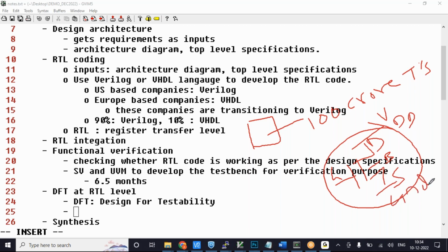For example, assume due to something, this also got connected to VDD. It was supposed to connect to something else. What happened? Because we are manufacturing at a very small level. What is the level we are manufacturing at? Nanometer level. What can happen? A metal got deposited here, some metal got spilled over. It's metal deposition, right? That's how a chip is made. These two got shorted. What will happen? Will this transistor work properly in that case? No, right? It won't work.